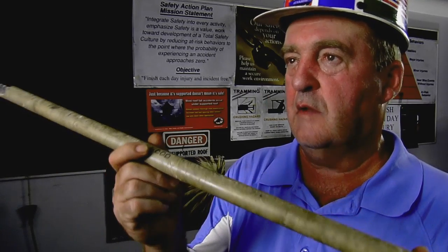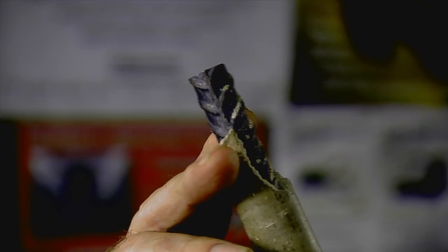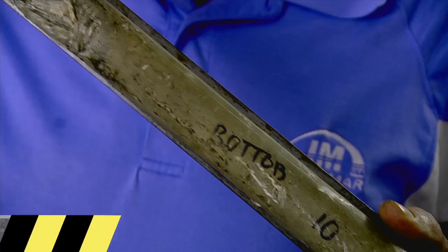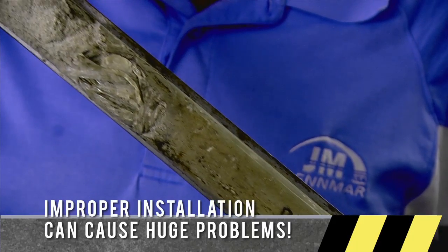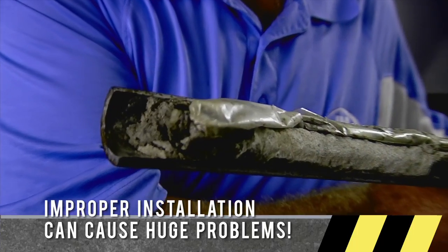This is a good installation of a rebar roof bolt. You can see that it's been mixed right from top to bottom. You can see where the rebar is holding real good with the resin. This is an improper installation of a rebar bolt. As you can see, it spun good in the beginning, but as they went up, you can see it just gets worse and worse as you go.